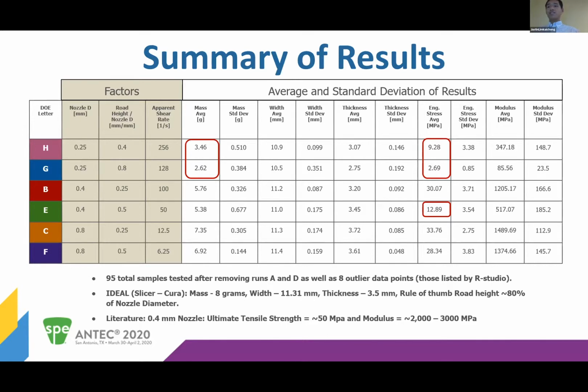And you can see that huge decrease in terms of tensile strength. So from around 30, once you set it around 25%, you see that once you increase that layer height, you see almost an 18 megapascal decrease in tensile strength. Furthermore, you can see that there is some correlation between your tensile strength and your modulus decrease. So again, you also see the parts were very flimsy at this point, and they would be very easily ripped apart if I had to give you these parts right now.